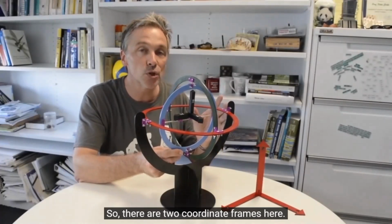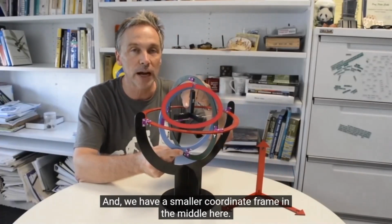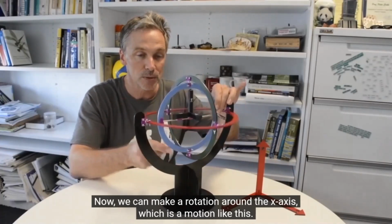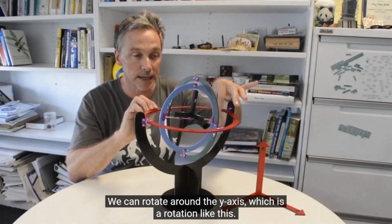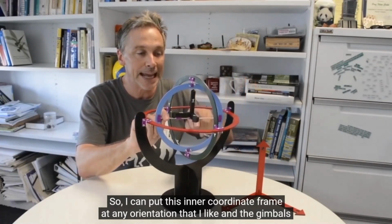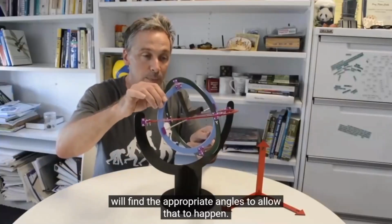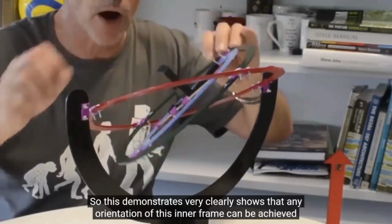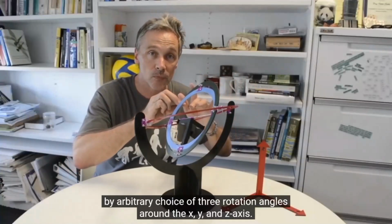A way to demonstrate this principle of three consecutive rotations is with this mechanism, I think called a gimbal mechanism. So there are two coordinate frames here. We have the world reference coordinate frame here, the big red frame, and we have a smaller coordinate frame in the middle here. Now we can make a rotation around the x-axis, which is a motion like this. We can rotate around the y-axis, which is a rotation like this, and we can rotate around the z-axis. So I can put this inner coordinate frame at any orientation that I like, and the gimbals will find the appropriate angles to allow that to happen. So this demonstrates very clearly that any orientation of this inner frame can be achieved by arbitrary choice of three rotation angles around the x, y, and z axes.